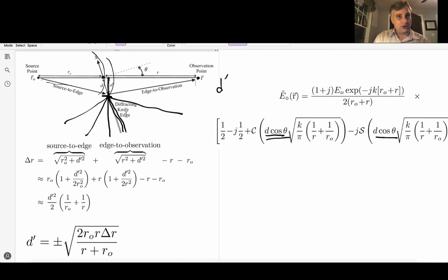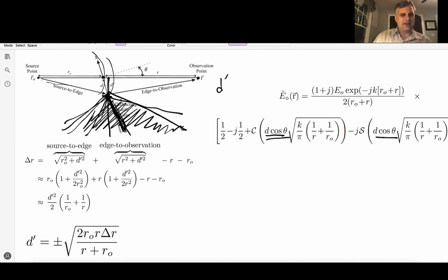Now keep in mind, when you do reintroduce realistic boundary conditions more precisely, then there is a dependence not only on the composition and the polarization of the interaction of this wave with the half screen, but its angle and even its thickness. Like according to the Fresnel formula, this could actually be a blocking wedge instead of a knife edge, and you get the same result. But in a precise electromagnetics problem, the width of this wedge, the angle between the facets of the wedge, actually affects the radio wave propagation and the diffraction solution. But this is a really good first order approximation.